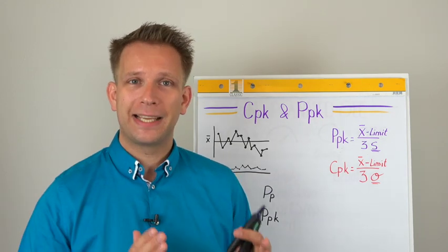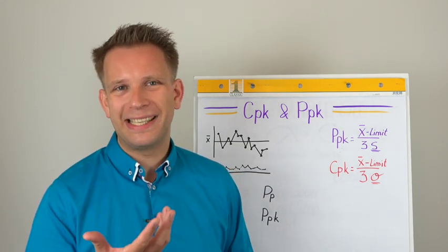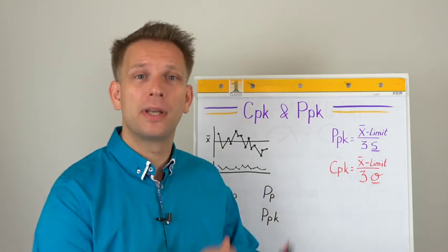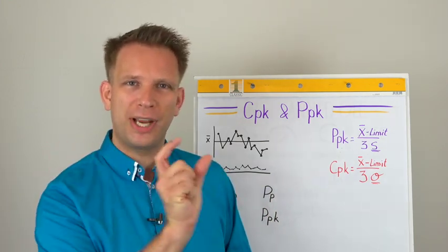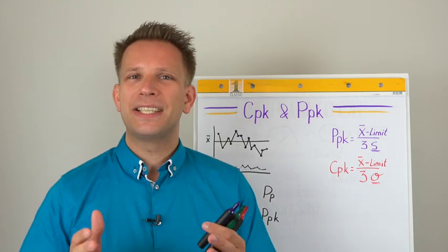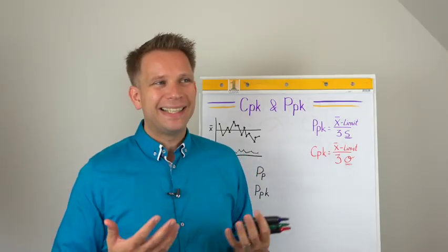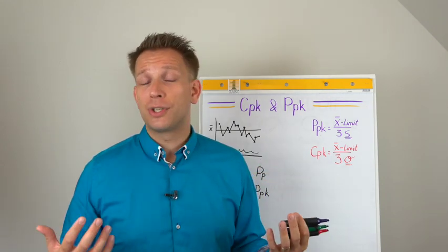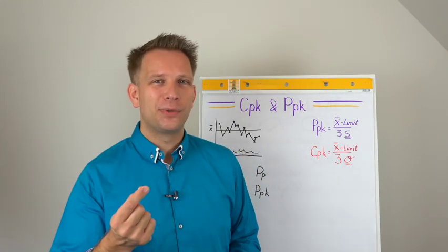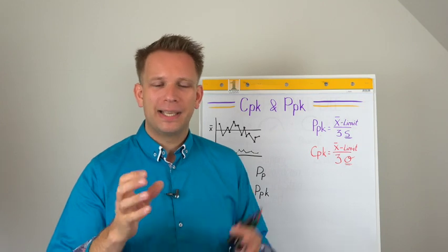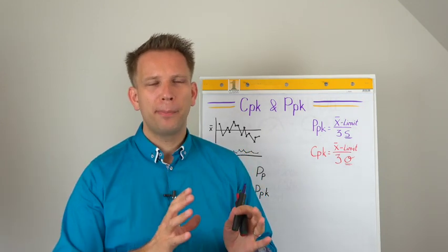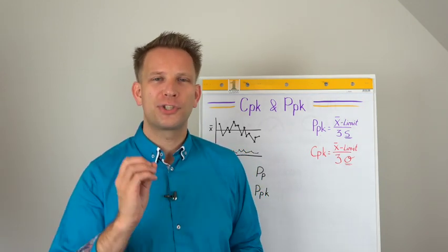The process capability index, the C of capability, P of process, K for this index that you check which side it goes off to. This takes samples from your regular process, and it basically takes samples over changes in your process, but the way you sample and calculate makes that you actually check short-term capability, so short-term stability of your process.